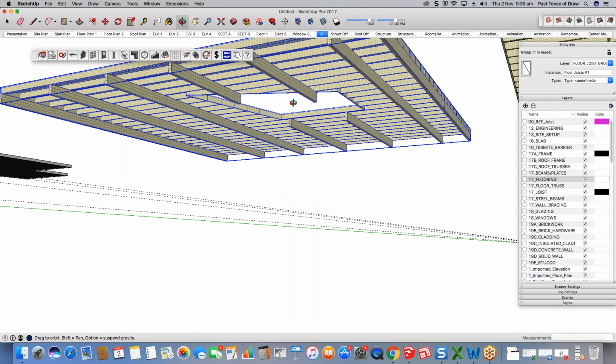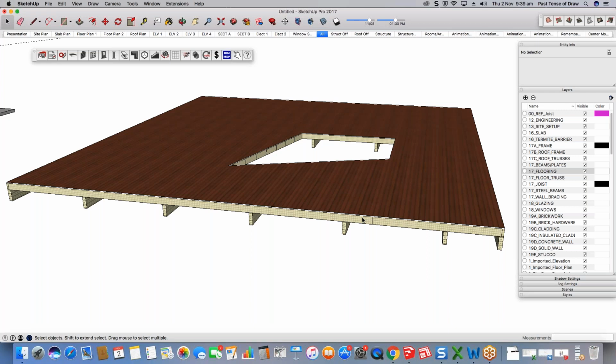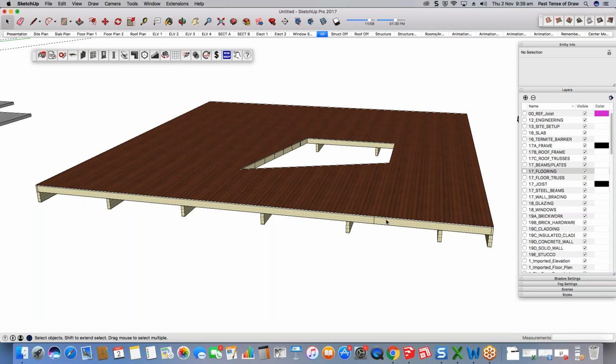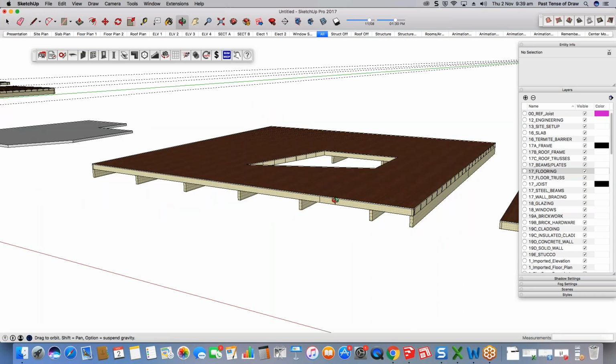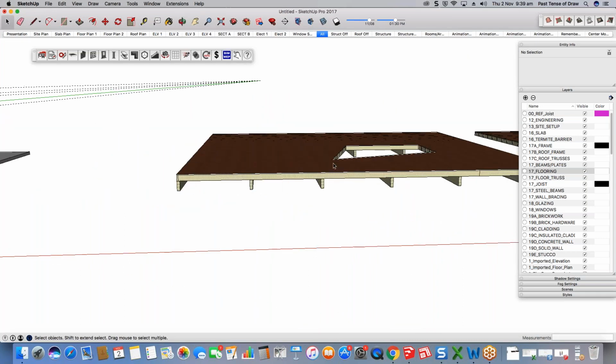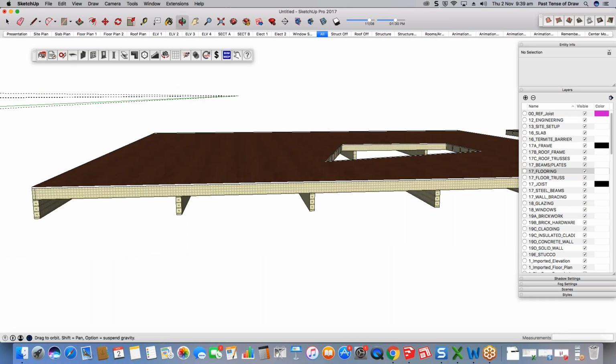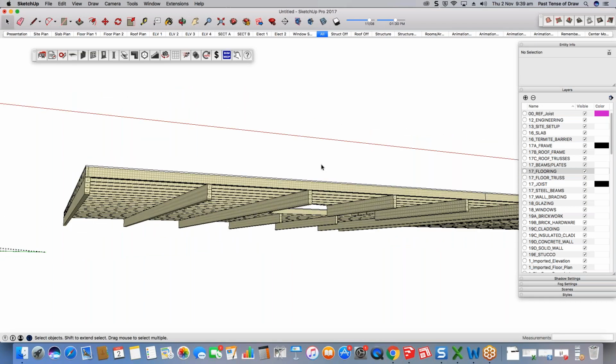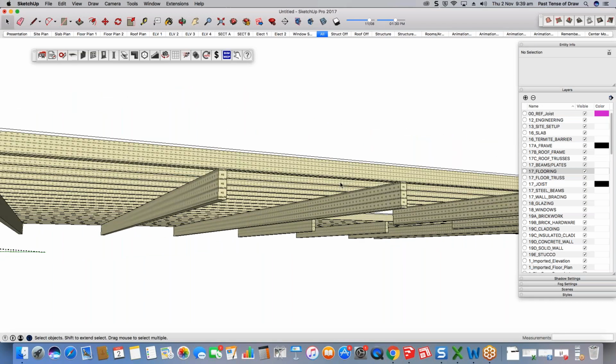Now, the problem though, is that it's removed or deleted any of those additional structural items or changes that I've made. So typically you want to do those at the end of a project, once it is less likely that you're going to have to be making design changes. Alternatively, if you're wanting to add additional structure, it can actually be best practice not to do the manual overrides and instead go into the new beam tool.